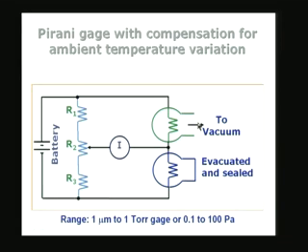So, in the case of the Pirani gauge, we essentially have two RTDs, or resistance temperature detectors, like structures here. These two are heaters. The temperature of the wires changes in response to the vacuum pressure, and therefore, the resistance changes. Because of that, the Wheatstone bridge circuit is going to go out of balance, and the imbalance is measured by the current which is shown here.